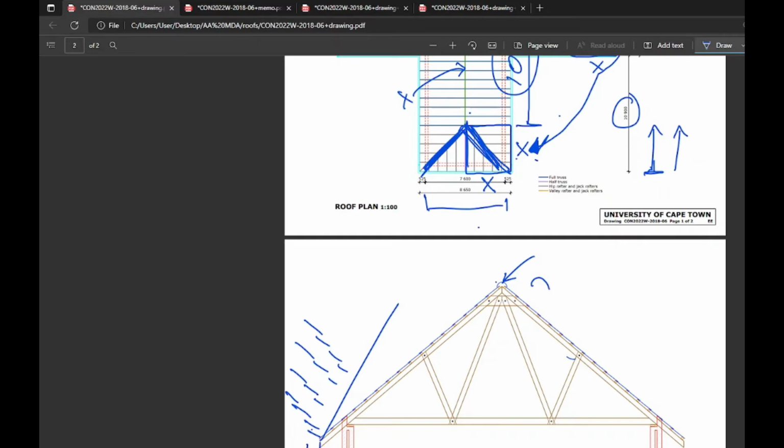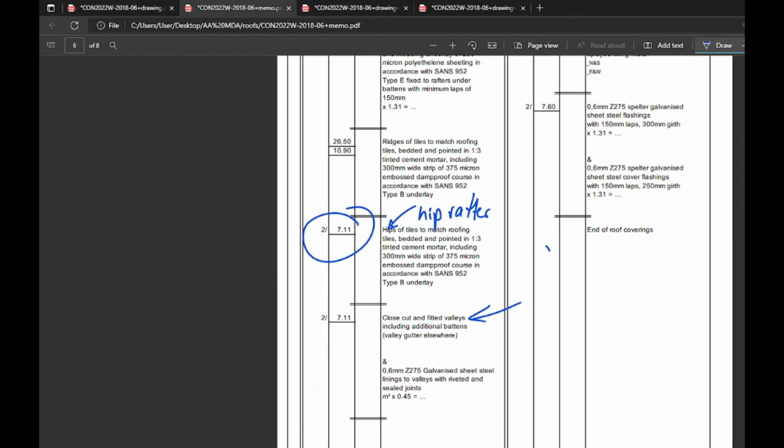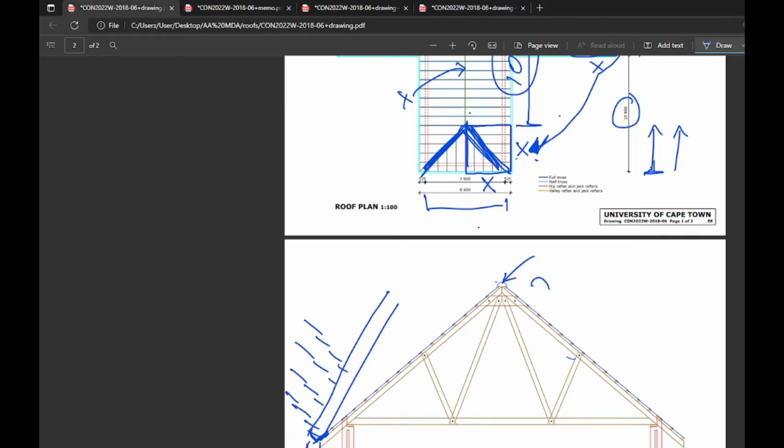And it is unnecessary because what you do is rather put a thin sheet of steel. The description specifically is galvanized sheet steel lining. Okay? Thin piece of steel that runs along. So they obviously have to fix it early and then lap the tiles over it. Okay? This terrible drawing. And so when the water runs down, it bounces and it goes past the last tile actually into a little steel, let's call it valley lining, and then after that it runs along the lining and out.